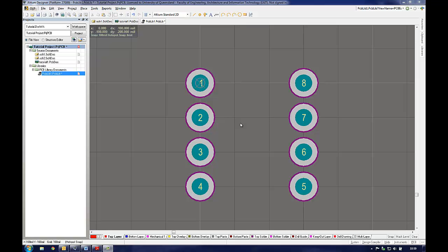The design of the body shape should be made in such a way that a person soldering the components to the PCB will know the correct orientation and rough shape of the component. Use the measure tool to check any distances used in the design of the component body. This can be accessed by pressing Ctrl and M. Right-click to stop using the tool.